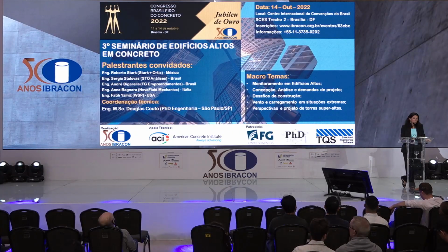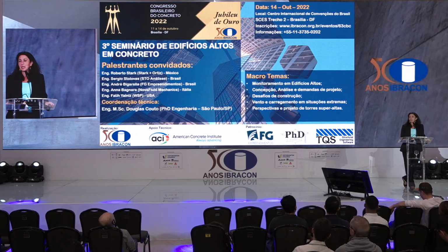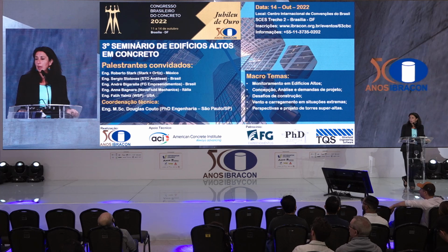Okay, it's a very interesting question and it's an extremely difficult question, and if you ask probably 10 or 20 wind engineers, they'll give you different answers depending on whether they have a wind tunnel or not, to be brutally honest. We have a CFD group, so we do CFD. But we use it only for wind comfort, not only for wind comfort, we use it for many applications, but certainly not for wind loading. It's simply not quite there, the technology.